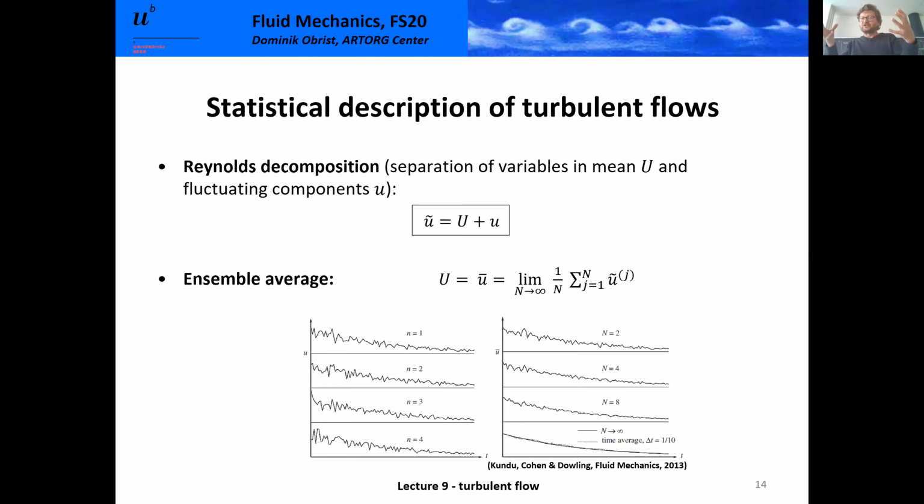You take the whole Navier-Stokes equation, and wherever you have the original u, or here u tilde, you replace it by U, capital U, mean flow plus fluctuation, right? There's no magic behind that. You just replace variables. And then you multiply that out, you split the terms wherever you can, and then you average the whole equation, left-hand side, right-hand side, in an ensemble average sense.